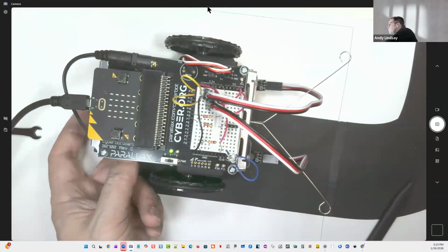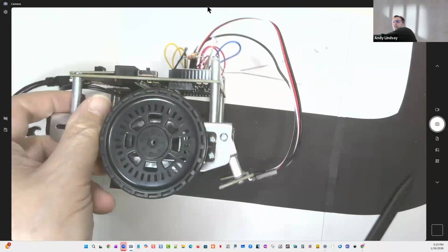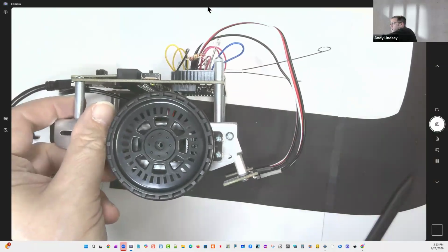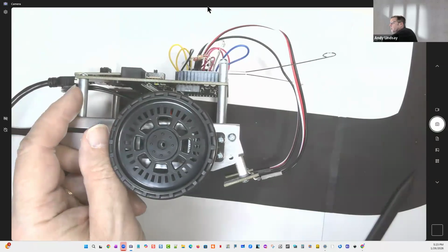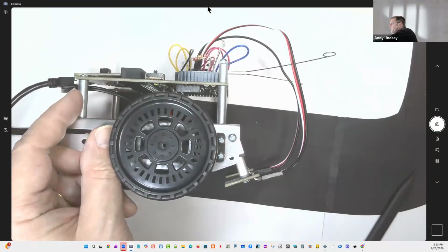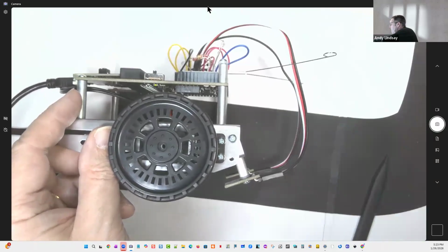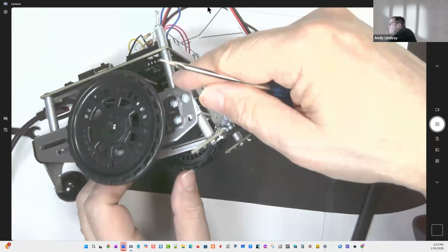So all I did was, see how my QTIs are tilted a little bit forward now? Probably at about a 20 to 30 degree angle. That gave me nice solid detections of the white paper on the periphery.